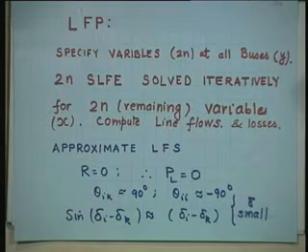Secondly, you need to know line flows for protection reasons. You can't have overloading of transmission lines, otherwise security problems will be there, power system security. What are the two problems? The frequency variation also creates a security problem. Frequency should not vary beyond plus minus 0.5 hertz. In India, of course, it varies from 47 hertz to 53 hertz, but in the rest of the world it is 49.5 to 50.5 hertz, and in the US of course 59.5 to 60.5 hertz, where it is 60 hertz.